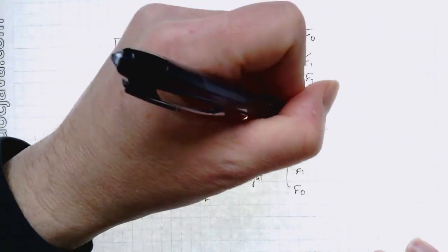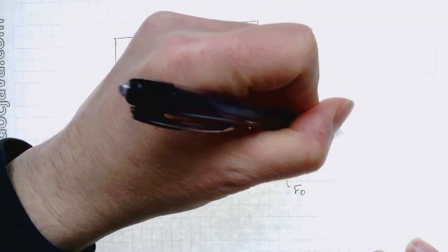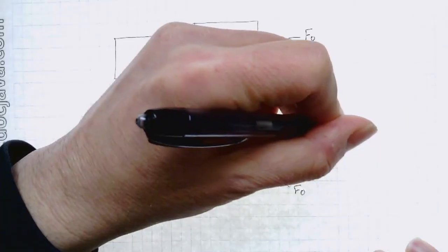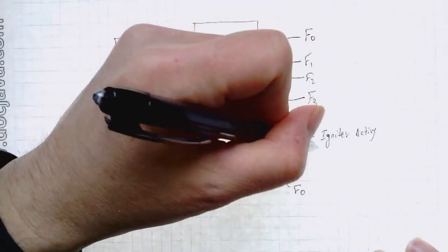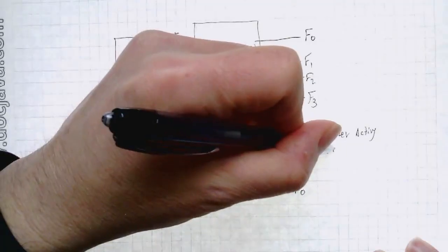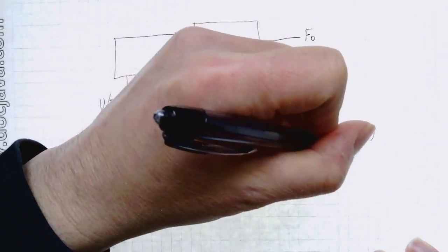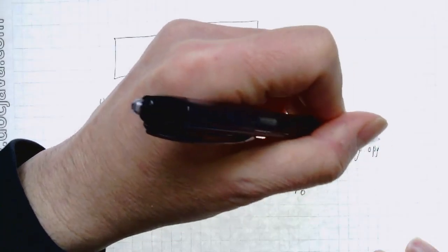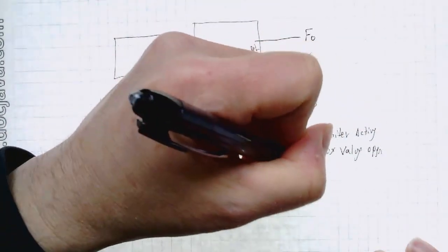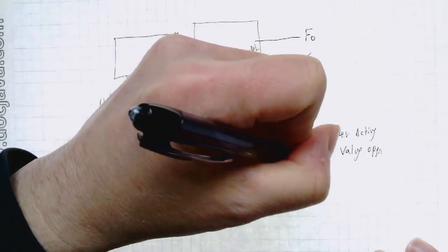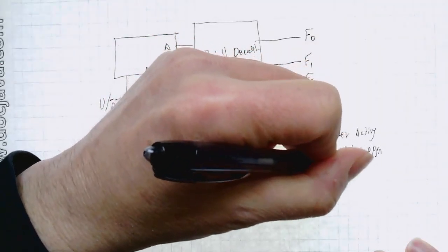And so what we'll do is we'll ignite. So the igniter active. That's our ignition sequence started. Now we'll take the LOX. This is not the smoked fish, it's liquid oxygen. And the LOX valve will open. In comes your oxidizer. To start our turbopumps, we use a fuel that ignites on contact, known as a hypergolic fuel.